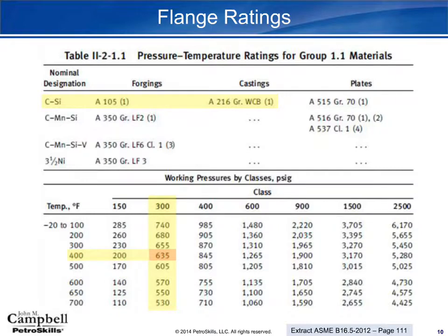So many times I'm talking with people and they say, what's the MAWP on that flange? And they say, oh, it's class 300, it's good for 740. And the reality is that varies based on, well, what is the design temperature? And having some cognizance that this is a line that is curving downwards from 100 when you make that selection.